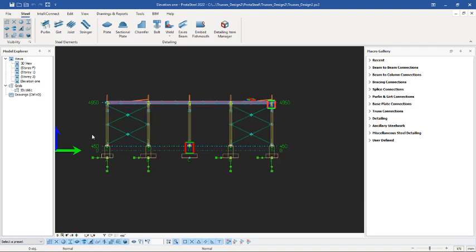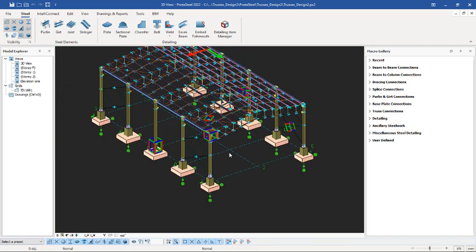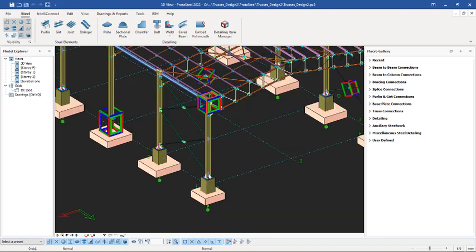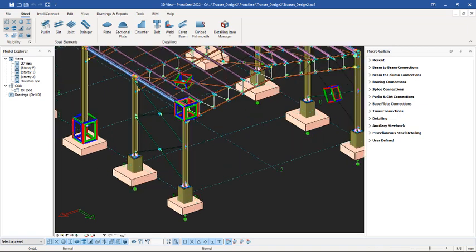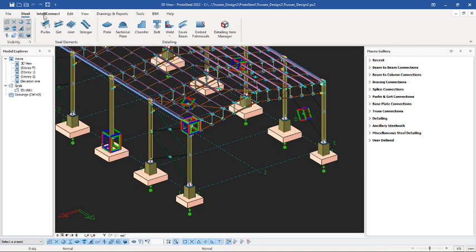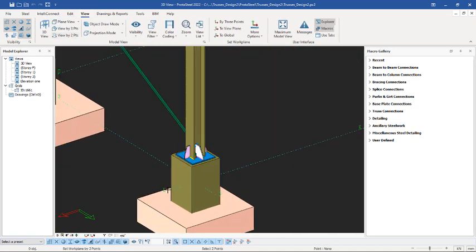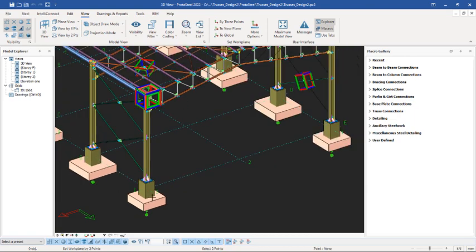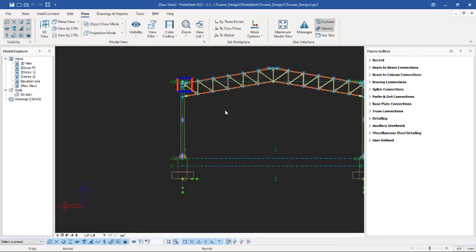I will be showing you how you can get that the same way I got this length elevation of the structure. So let's get back to the 3D right there. We have this, so this way is the width and here is the length. The one that we've gotten so far is the length, which is on grid line 3. All right, so we are going to be having another section at grid line E. So we go to the view right there, and then you click on view by 2 points. Okay, so you zoom closely to grid line E at this point, pick that point, come over to this other point and pick that. So it's going to view it for us just like this.